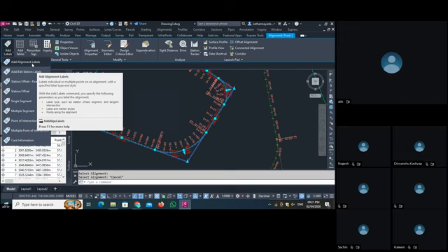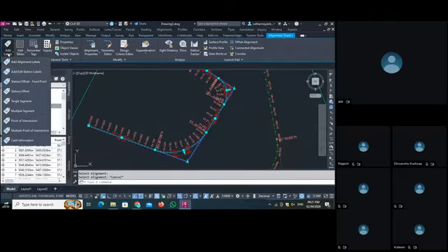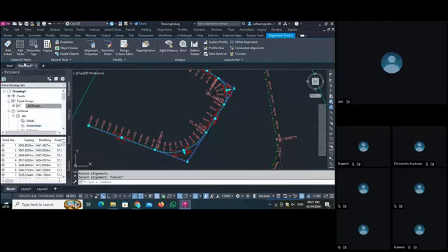And with that decent work we have to provide all those points. So how is it possible? We can create a table also. Near our alignment we can put that table, so the contractor or the client can check the table and understand the alignment behavior. So for that we have to go to add label and add alignment label.